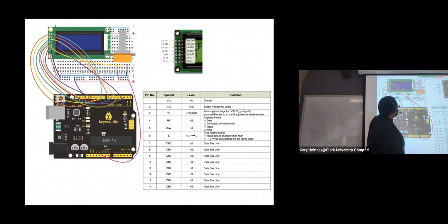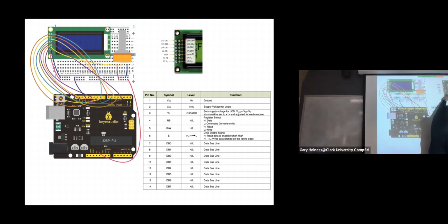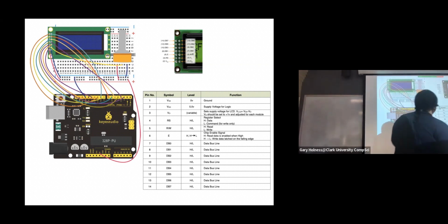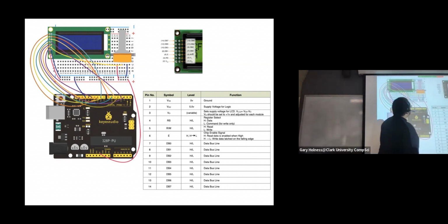Let's look at what feeds the device itself. So we said pin 1 is ground and pin 2 is +5 volts. And so here, pin 1 is the blue. You'll notice that's going to the negative rail, which is ground on the breadboard. Pin 2, that's voltage, VCC, or VDD sometimes it's called, and that has a jumper to the positive rail on the breadboard, right? So next, let's look at this variable input.